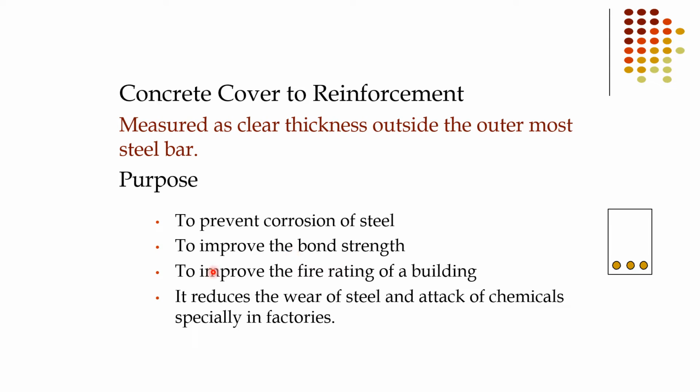To improve the fire rating of the building, if you provide a higher thickness of cover, then your fire rating is good. But normally, for a 2 hour or 3 hour fire rating, the minimum cover will give that rating to the building. So that will also improve by providing the concrete cover.